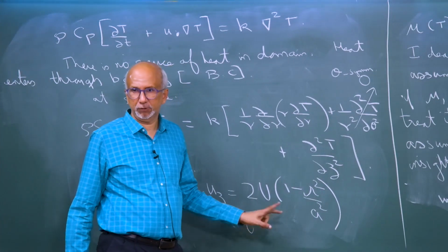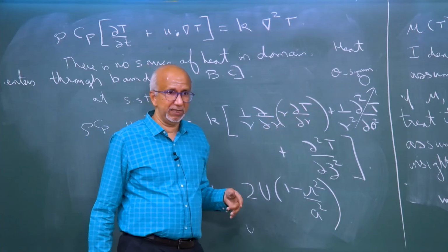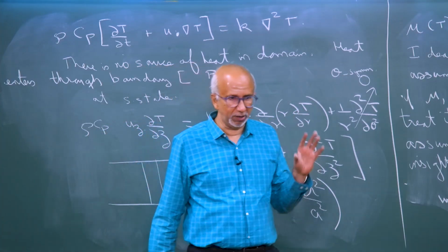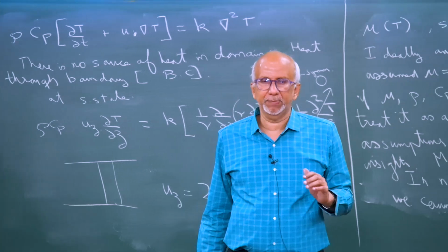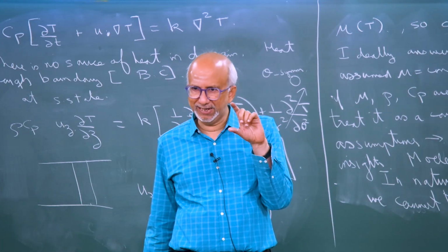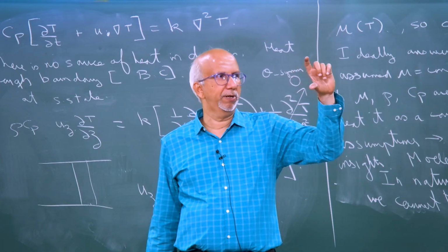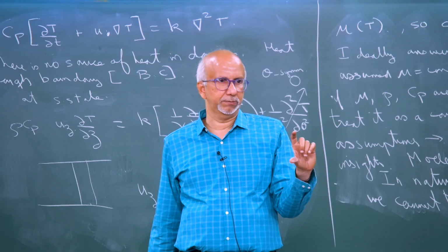Okay, this is my velocity profile. This is coming from my laminar flow by solving the Navier-Stokes. So, basically what I have done, if you look at it mathematically, by making this assumption that viscosity is independent of temperature, I have decoupled the momentum equation from the energy equation.